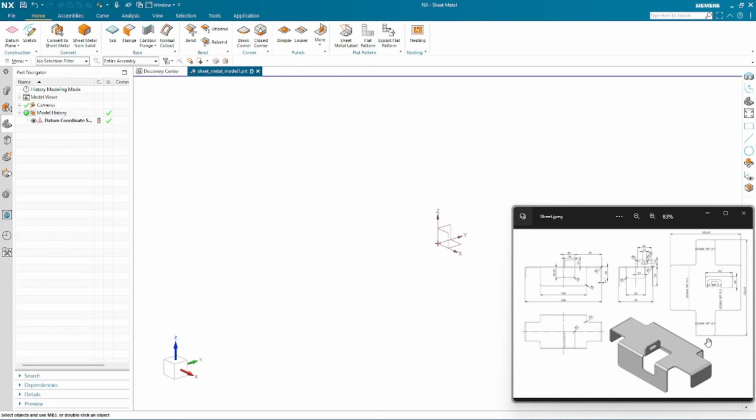Then I will create these cutouts, then the flanges, then this cutout, and finally this small flange. After this small flange, the oval slot inside it. Then our finishing features, like the radius given here at the corner, will be placed at the end as dressing up features.